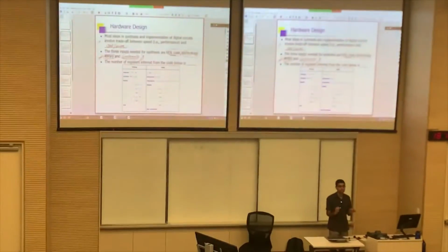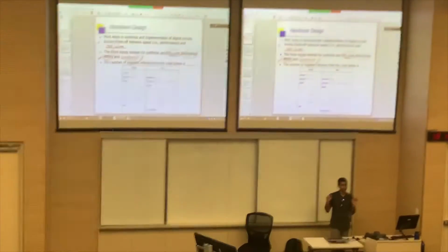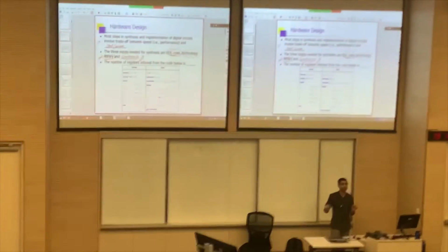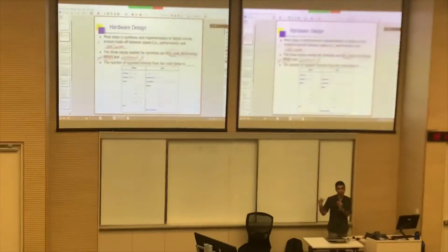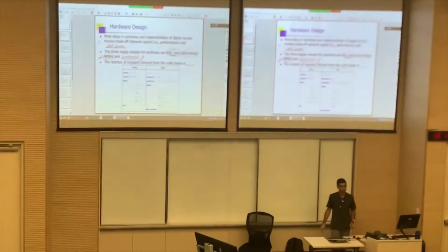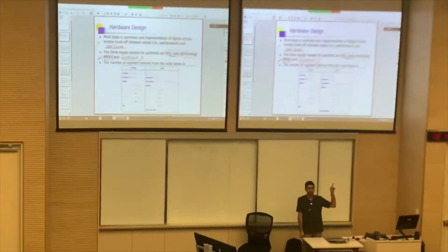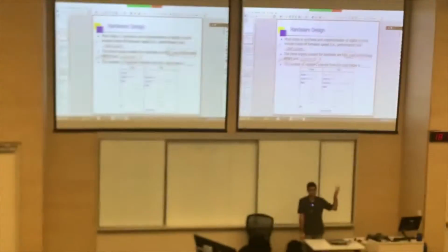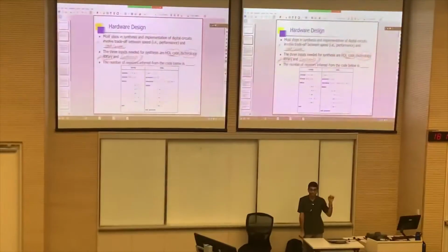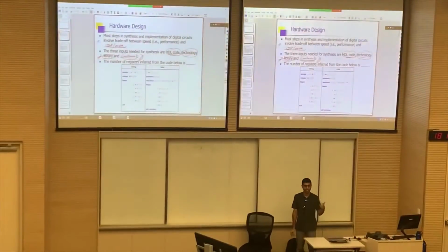Constraints are very much technology dependent. You put in constraints based on the eventual hardware platform that you want to create or run it on. So if you go through the constraints file in your project, there is a .xdc file. Some of you might not have opened it. If that is the case, please do open it and have a look to see what is inside.